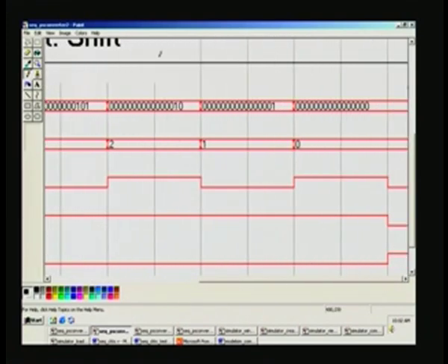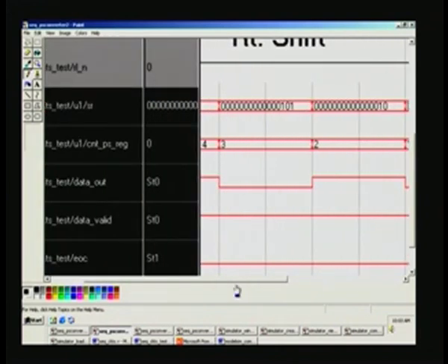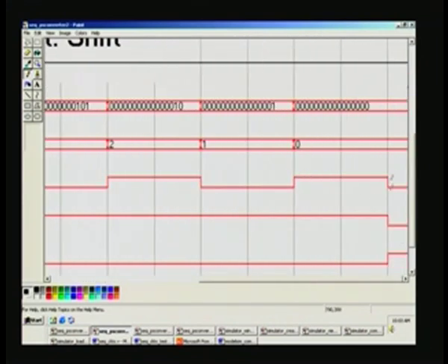Now, coming to the end, 1 0 1, then 1 0 is in the shift register, and then comes 1 because 0 gets dropped, finally 1 also gets dropped. So, ultimately it will be 0 here, and the last bit that will be sent is this one. We started with 1 0 1 0, so the last bit will be the MSB. So, naturally that should be the 1 here. So, earlier we saw that, okay.